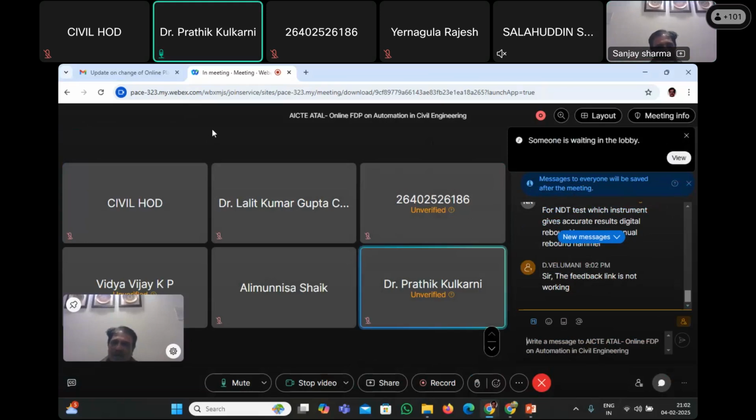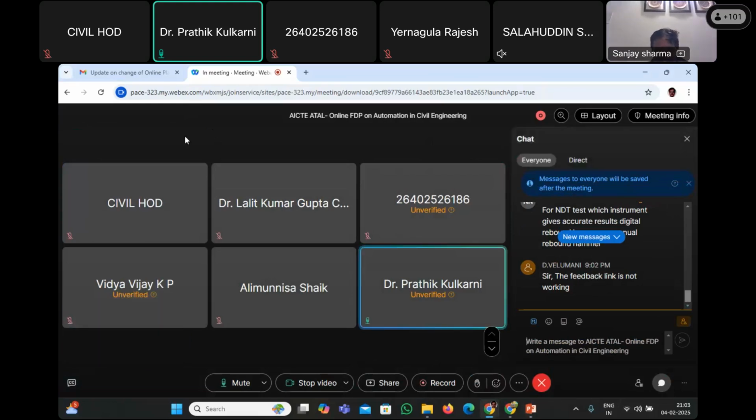We have done visual inspection. The bridge was at least 75 to 80 years old. There was no cement over there; it was purely constructed with lime. Through visual inspection, we did a carbonation test. We conducted tests on the decks which were available. We conducted UPV. We even did core cutting, using a core cutter.